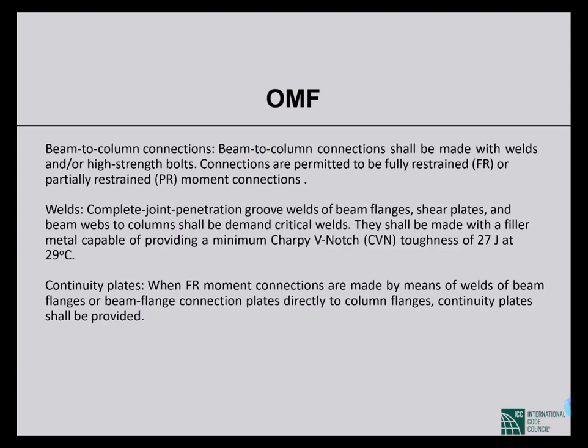Beam to column connections shall be made with welds or high strength bolts. Connections are permitted to be fully restrained or partially restrained. So even for the seismic case, partial moment connections are allowed for OMF.